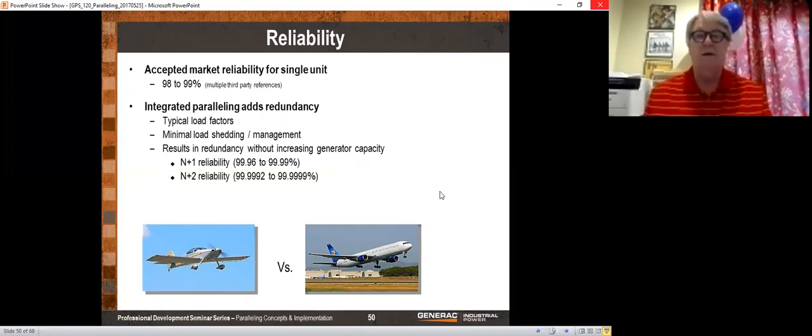That's because if we look at dollars per kilowatt, on a diesel generator it is lowest in the 400 to 600 kilowatt region. So below 400 to 600 kilowatts, it costs you a little more per kilowatt to generate that kilowatt. And as the generator gets larger and larger, you get a lower dollars per kilowatt. Once you go above 600, now you're talking about what we call big iron, things that are not commonly used in over-the-road trucks and front-end loaders and so on. And so you end up with a lot of handwork, the profit margins are higher, and your dollars per kilowatt then goes up. So we had a project, it was actually a chicken hatchery.